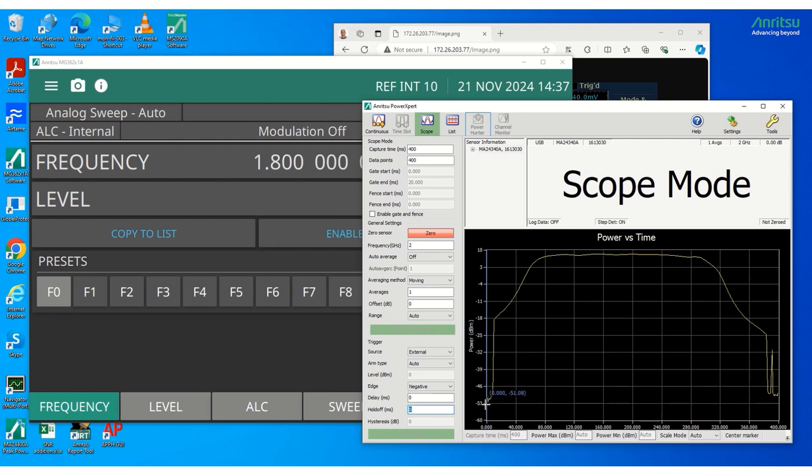And then your stop band is around the same point, right? 53 dB, and then 7 dB. So 7 and 53, 60 dB dynamic range. You could get even higher by going higher in power. So you might get all the way up to 70 dB of dynamic range here with this measurement.